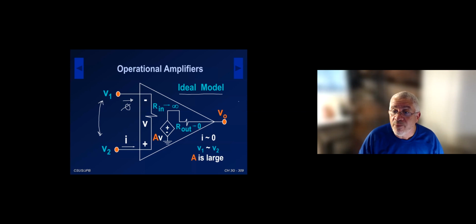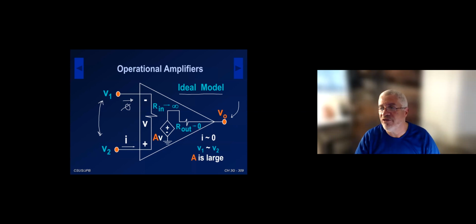So here, pretty soon I'm going to tell you no KCL here because you have a voltage source at that node connected to ground, all right? And then because the op-amp has such a large gain, we're going to assume the voltage at the input is very low, low enough so that V2 is about equal to V1, okay? So those are the rules that we're going to use when we solve problems with the op-amps, okay? So, again, let me just show you that in a more succinct way.